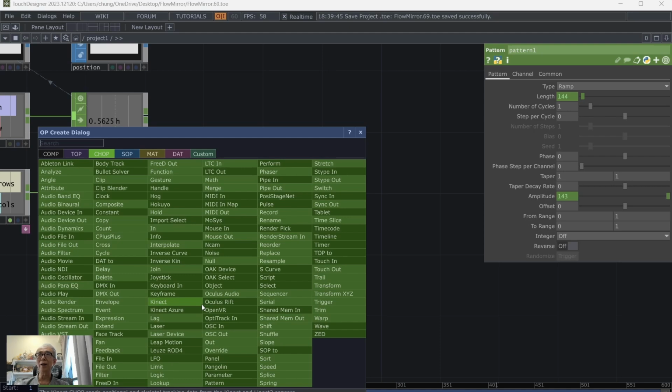So that is, we need to divide the instance ID or instance number by 16 to get the row, and then we take the remainder of the instance number divided by 16 in order to get the U coordinate. So that we are going to do now. With this one we're going to add two expressions. There are two ways to do so. One is an expression, and the other you can do the normal math with multiplication and subtraction. And I try to do the faster one with two expressions.